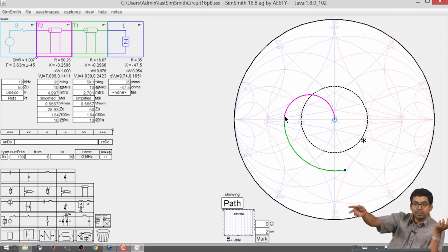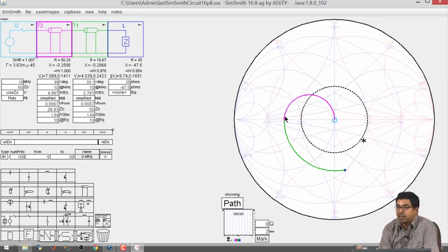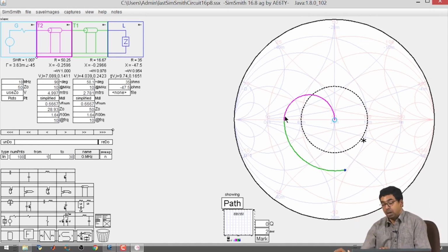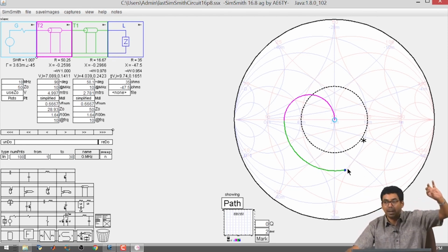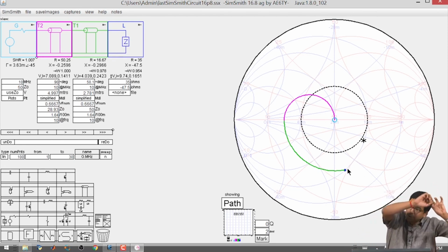So you can use either of them, and then you can use a quarter wavelength transformer after that to match. Okay. So a complex load can also be matched with the quarter wavelength transformer, provided you figure out that the complex load can be made to look resistive first with respect to the generator, then you use a quarter wavelength transformer to match.